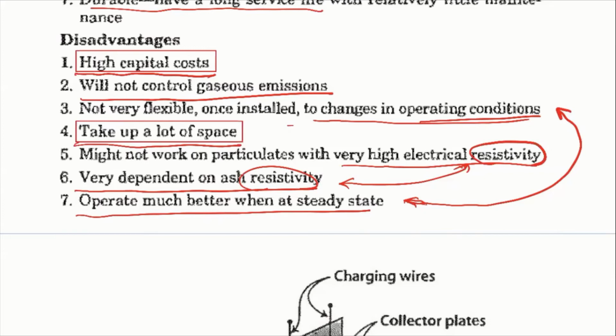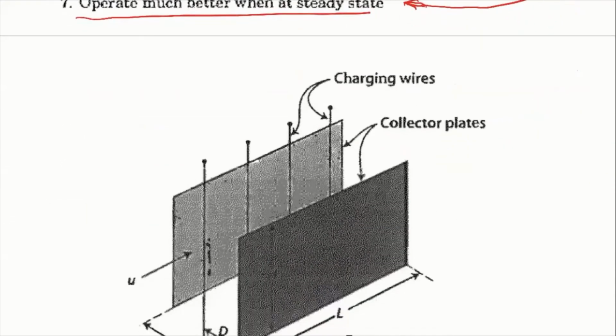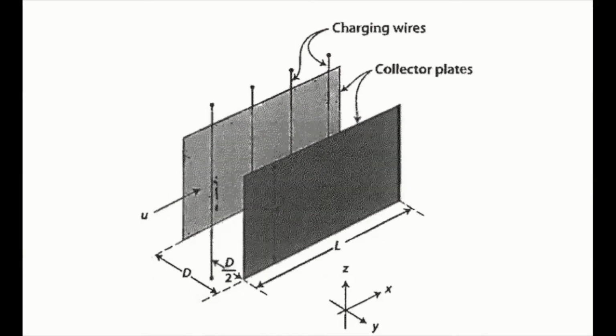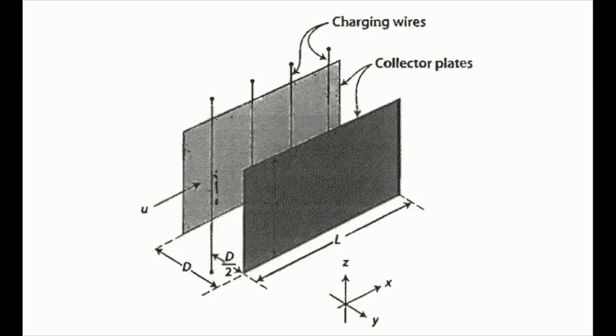Since we talked about the removal rate or the removal efficiency, how do we calculate the removal efficiency? We mentioned that for the cyclones, there are equations to do that, right? We first calculate the dp50 and then calculate the collection efficiency at different sizes. For the ESP, what we're going to do is assume that particles have similar sizes, okay? And we're going to choose the simplest ESP geometry to calculate its efficiency, and then further relate this efficiency equation to practical ESP systems.